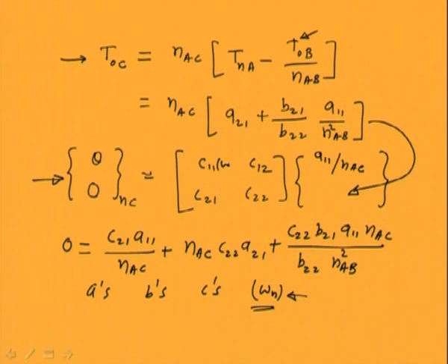Then once we have the natural frequency, we again have to go back to these transfer matrix equations, so that for a particular natural frequency we will substitute various terms, like here all C's are functions of omega.